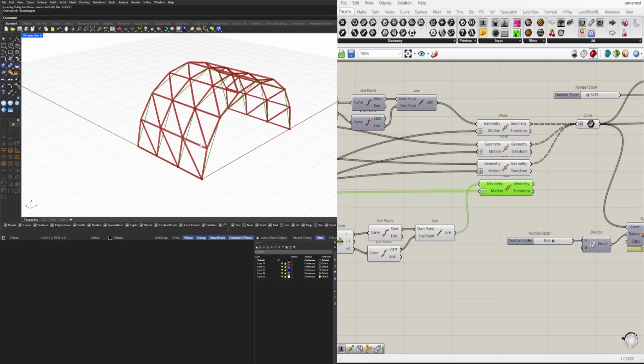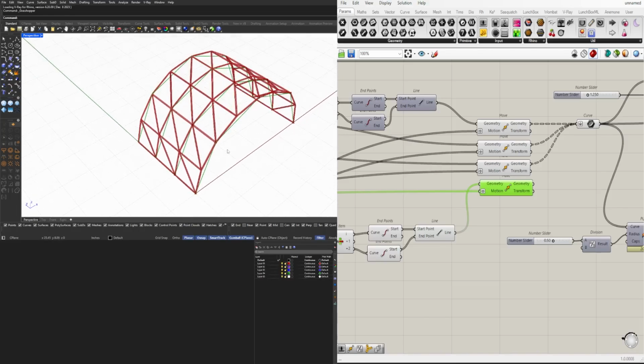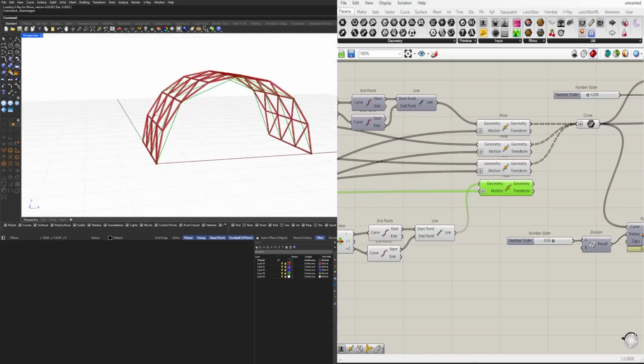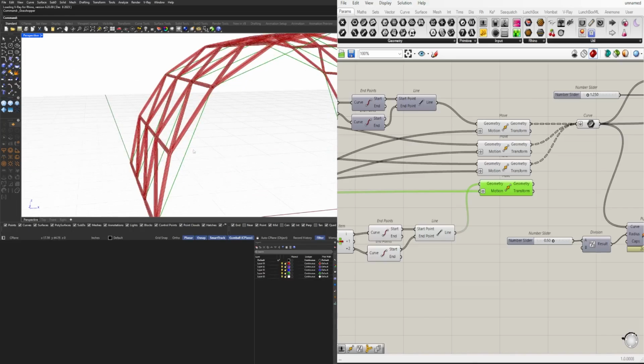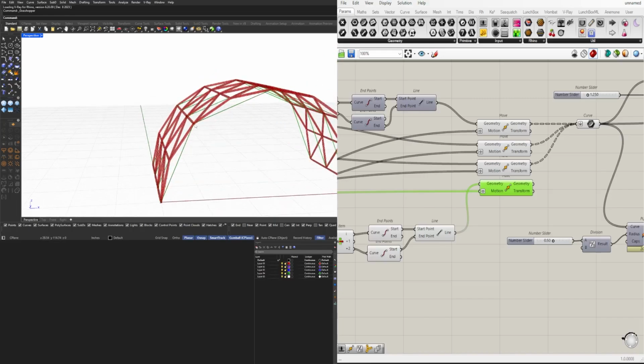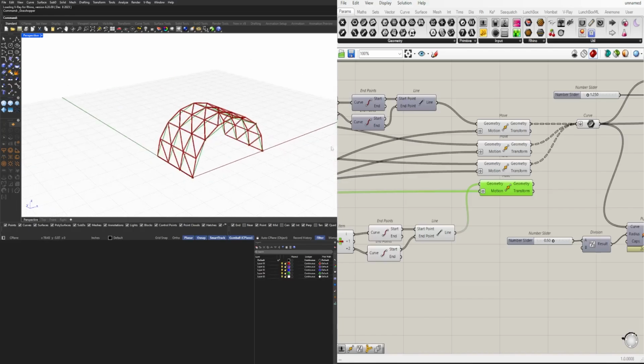So these are the arches, and these are more of the connecting segments. And this creates a bit of a truss system. These will ensure that the angle between these two remains, and also these bolts and these connections actually have to be a little bit longer, because these diagonals and connections would actually be below the entire pattern here.